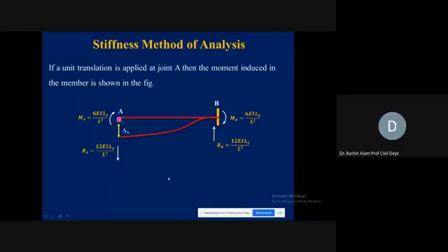Because you will be using this again and again, you need to quickly find all these values. If a structure is given, a member is given, first you need to look at the I value, whether it is 0.5I, 2I, or 1I, so accordingly you will have to put that in the equation. If a settlement is given, accordingly you will have to incorporate the settlement length. That specific length you will be given, you will look at it, and you will put that in this equation.